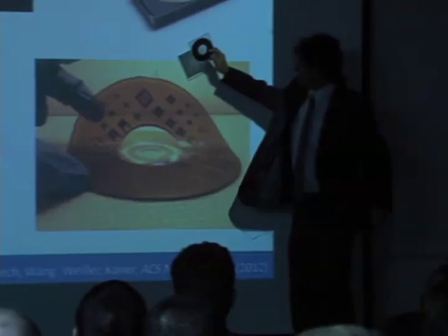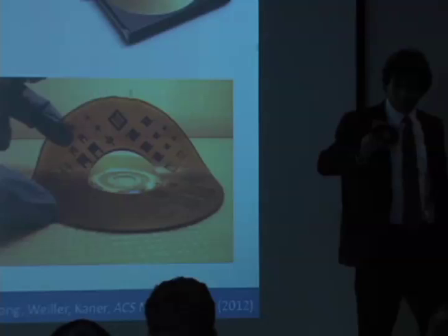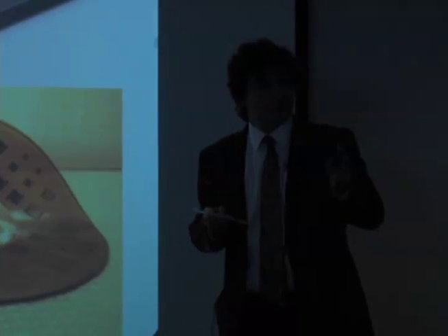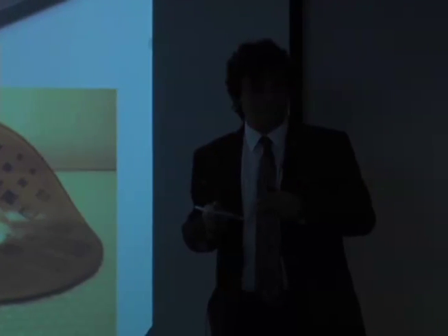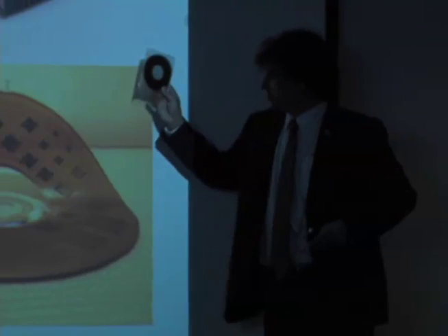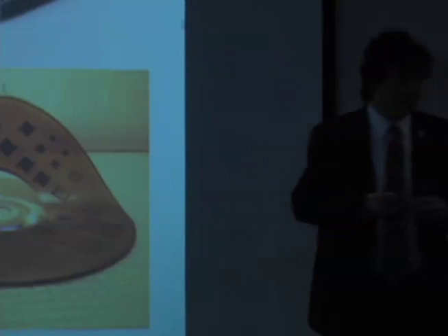And then my favorite picture of all is this one. So there's a little bit of lighting. And what this is now, we're going to graphite oxide. So with conducting polymers, they go from conducting, they melt, they become insulating. But with graphite oxide, it's insulating. We hit it with a laser, it gets hot, blows off CO2, and turns into a form of graphene, becomes conductive. So here we're actually drawing conductive lines. And my students have this interesting sense of humor, so they drew graphene out of graphene.